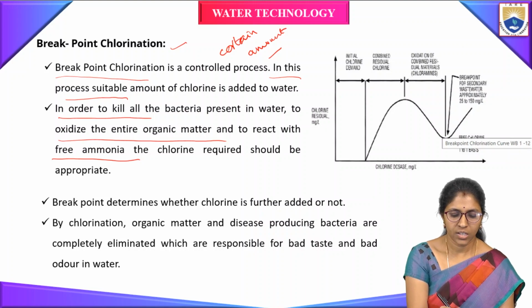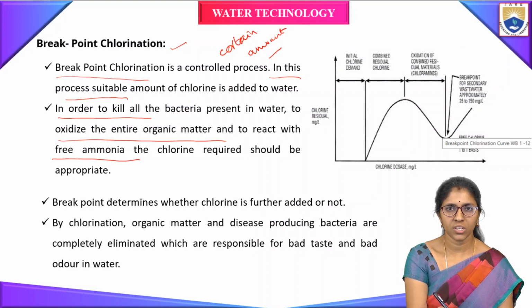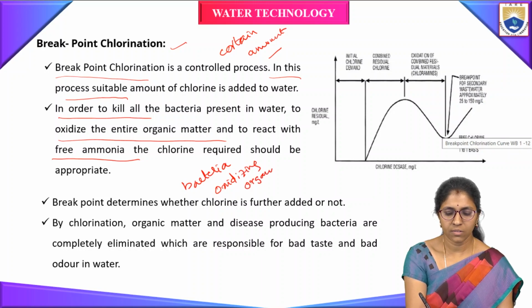So by using breakpoint chlorination, we will remove the bacteria. It is also used for oxidizing organic matter, and it also reacts with ammonia.